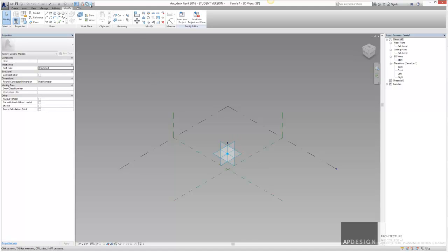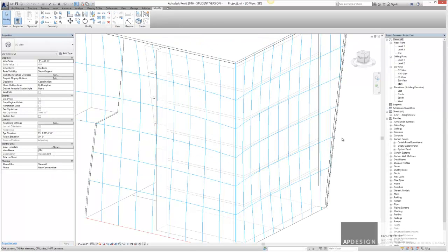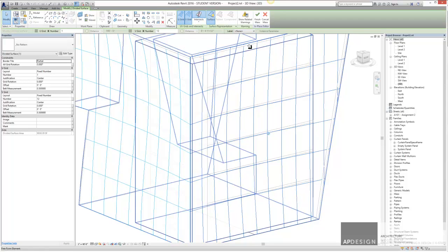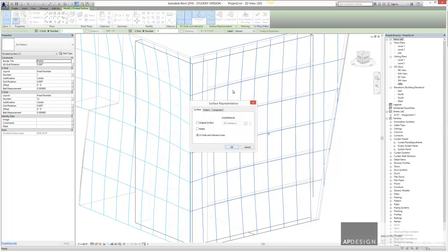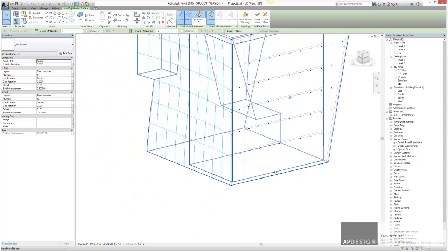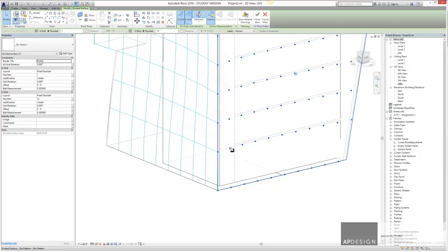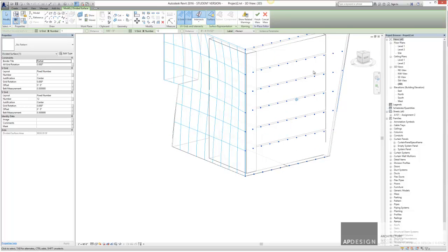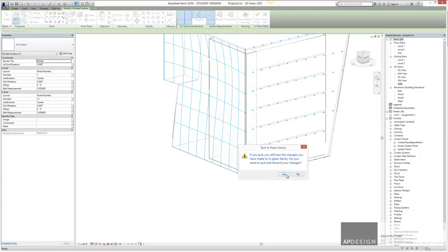The importance of that is that let's turn to the project 2. And in your current project, you should have like a grid of some sort like this. So if you click on that grid and you get into that surface, you can turn to representation and turn on nodes under surface, and turn off the UV grid. And you'll see these points, this point array. Well, the importance about this adaptive component is that essentially by just adding the component we're about to make to one of these nodes, we can populate the world with it, and it doesn't matter where it exists in the world, it will adapt to it. So that's pretty cool.